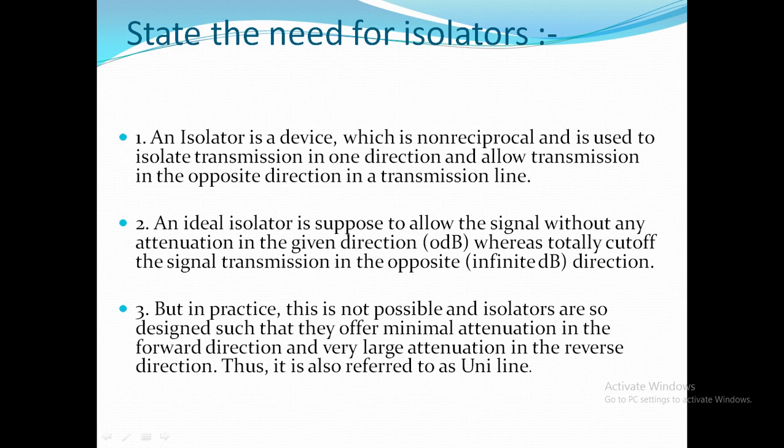Whenever an unmatched load is connected to the waveguide, reflected waves are generated from the load and returned towards the generator at the other end of the waveguide. Due to this, the frequency stability of the generator will be affected. In order to minimize the frequency instability, we use isolators.